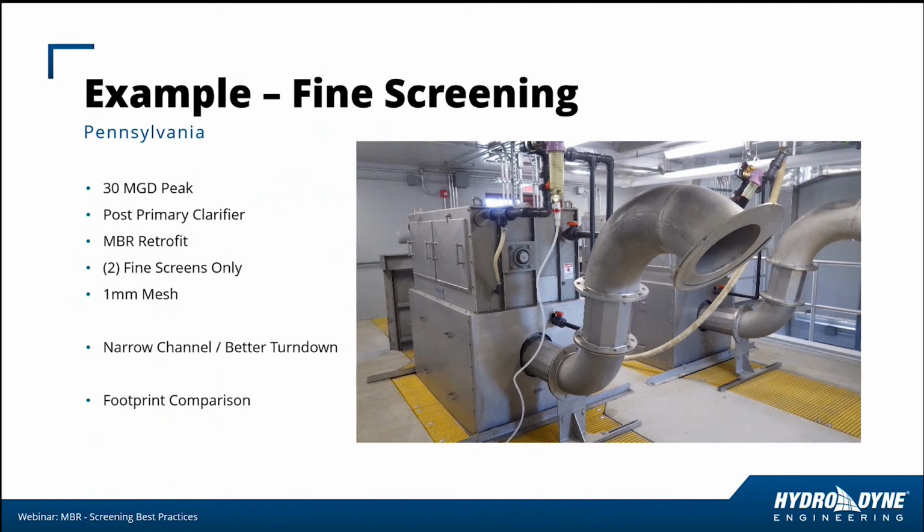So in this design, there were narrow channels, and that provides better turndown. And what that means is the velocity profile for the screen is better at higher and lower flow rates. So there's a wider spread in flow that can be accommodated.